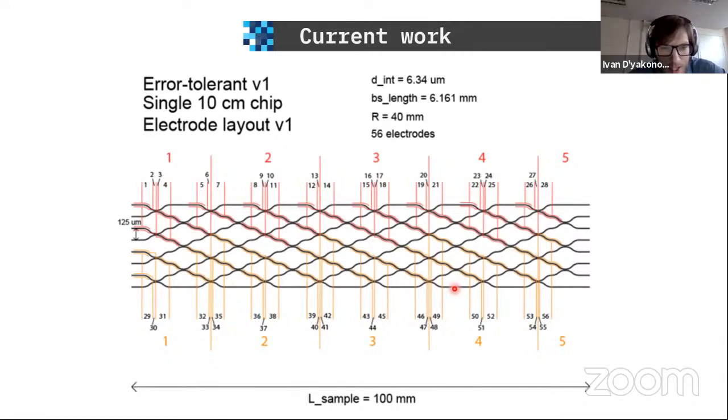We have not tried that yet, because a circuit of this size is quite complex on its own for our technology. So what we tried to do is reduce the width of the heaters, and also optimize the length. As you can see here, they are a bit wobbly. They have this wave-like shape to follow the path of the waveguide in order to make the length of the region where the arm of the interferometer is heated as long as possible.